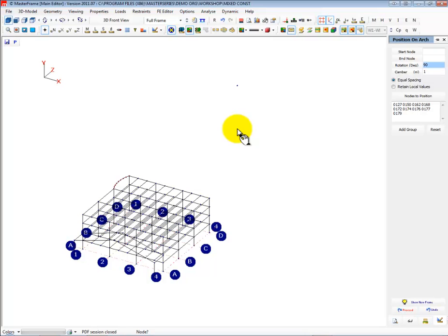Okay, this has actually brought up some interesting questions. And can you kink a super member? No, there is a slight tolerance allowed of 1 or 2 millimeters, but that's all. A super member must be straight. And somebody else asked, how do I design haunched eye and box sections? Well, the haunched eye and box sections, we cannot design them.